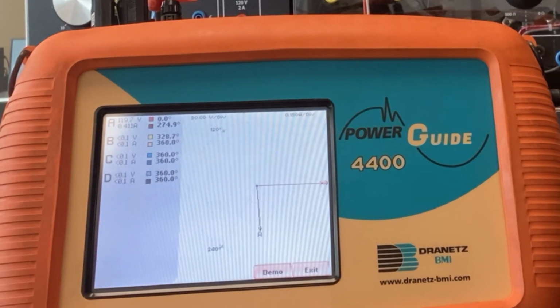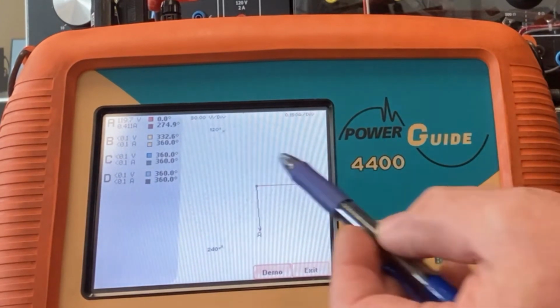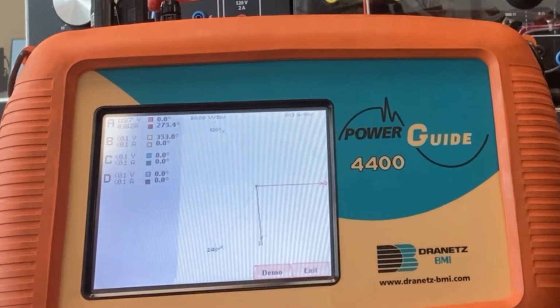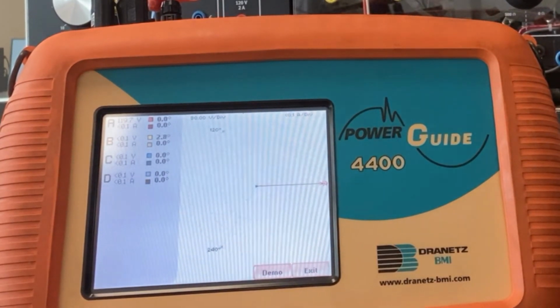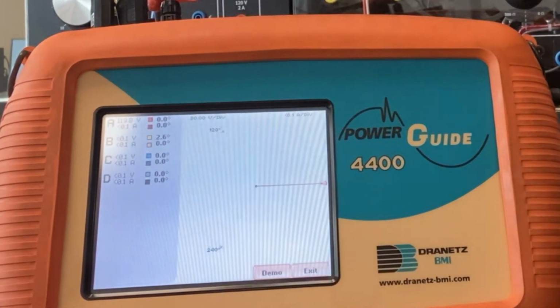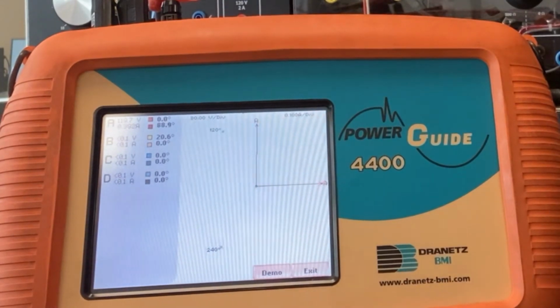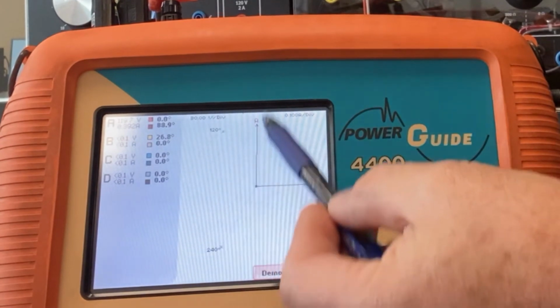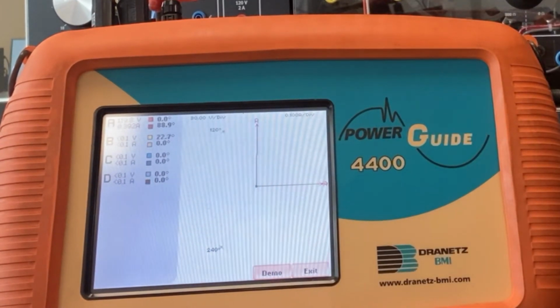Now I'm going to shut off the inductance and turn on some capacitance, and you're going to see it out of phase, but it's going to go the other way because we know that with inductance, the current lags, and with capacitance, the current leads. So here's our capacitance added to the circuit, and sure enough, it's off by 90 degrees, but the other way.